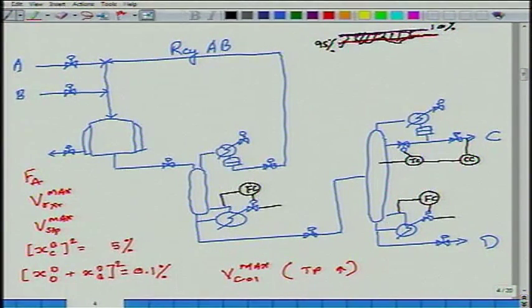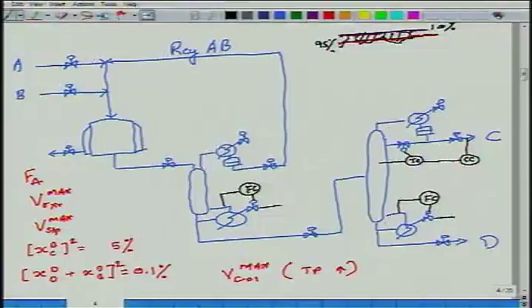Separating the concentration. Yeah, of course, the column separates. What the hell is it separating? Well, B is the lightest component. Whatever B leaks down is bound to go into C. It is preventing D from leaking up the top. Yeah. So, by adjusting reflux, what are you going to control? Amount of D. Let us say you say no, I am going to control the mole fraction 99.9%.